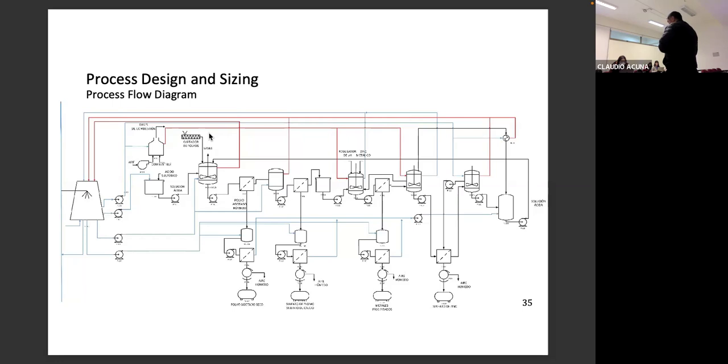Just round numbers. And the most important is the most important equipment, let's say the autoclave, and the largest equipment, let's say a SAG mill, for example, or the primary crusher. The primary crusher is the largest and most important, because it requires 2–3 years to build a big primary crusher, and from there you calculate the rest of the equipment. Usually the most important one will be 3 times the rest of the equipment, and then another 3 times for the facility, depending on the type of facility. If it's pharmaceutical, it will be 5 times because it requires better facilities.